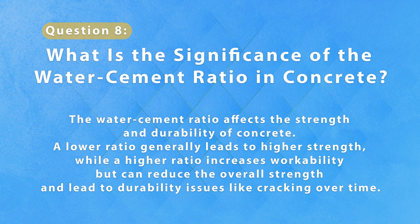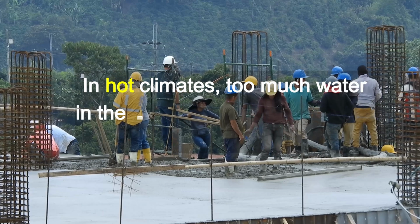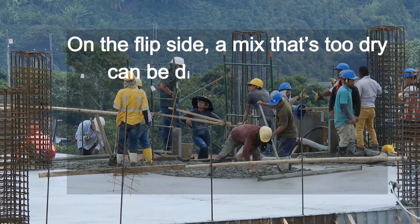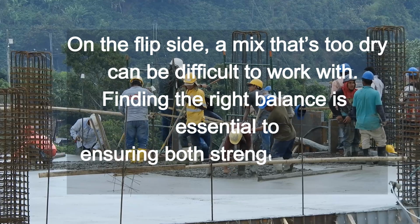Question 8. What is the significance of the water-cement ratio in concrete? The water-cement ratio affects the strength and durability of concrete. A lower ratio generally leads to higher strength, while a higher ratio increases workability but can reduce the overall strength and lead to durability issues like cracking over time. In hot climates, too much water in the mix can evaporate quickly, leading to cracks in the concrete. On the flip side, a mix that's too dry can be difficult to work with. Finding the right balance is essential to ensuring both strength and ease of use.